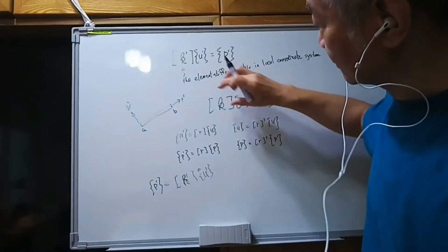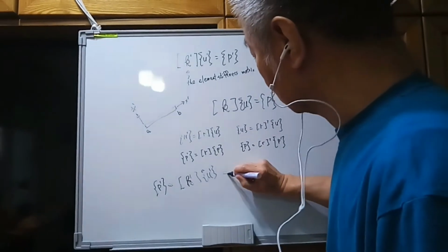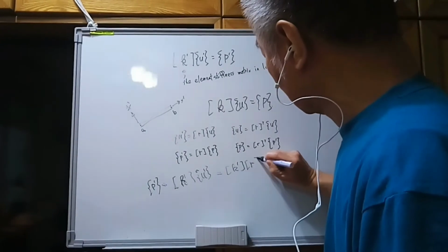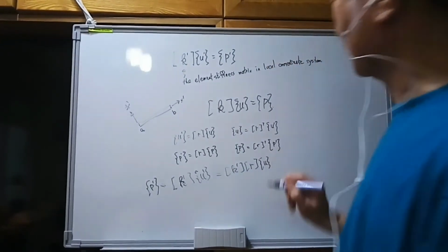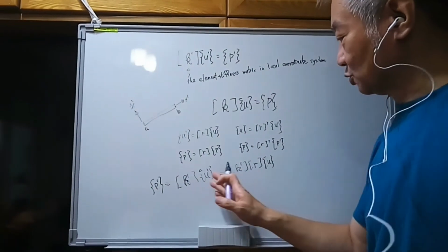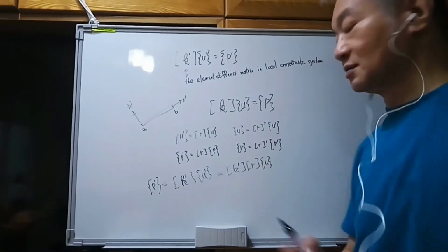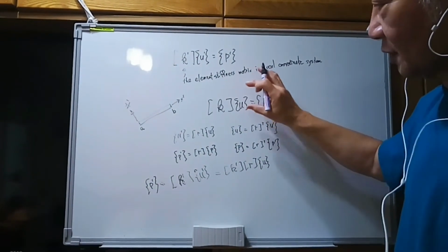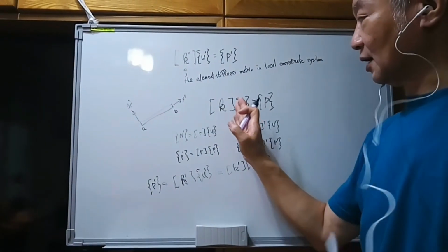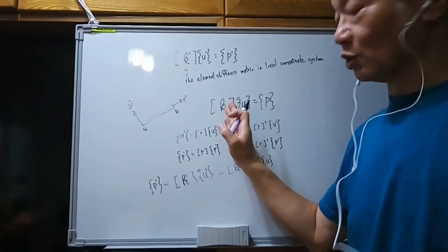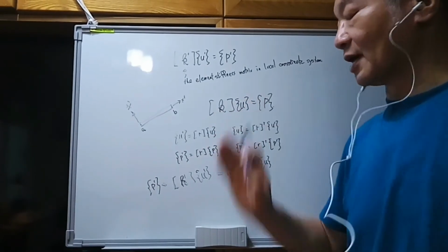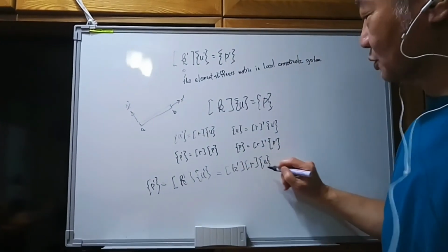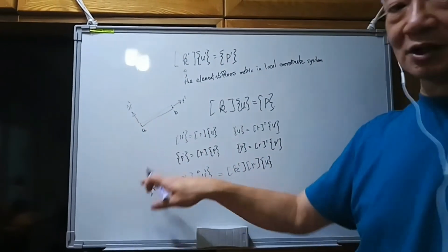If we like to move this to this one, first we can change it to the K prime, to the R, to the U. So first we can change the U prime by the R times U. Okay, so the post multiply vector, which is the target we like to get, the K in global coordinate system must be multiplied by the U. So K prime times R post multiplied by the U can give you the P prime.